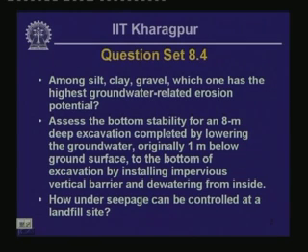eroded by groundwater movement. So as I indicated in the previous lesson, basically the soils that are the particles that are relatively light, as well as ones that do not have any tendency of sticking together, or cohesive. So those type of soils are most susceptible to erosion. So the soils that are non-cohesive and comprising of very fine grains exhibit the highest susceptibility of getting eroded by moving groundwater.